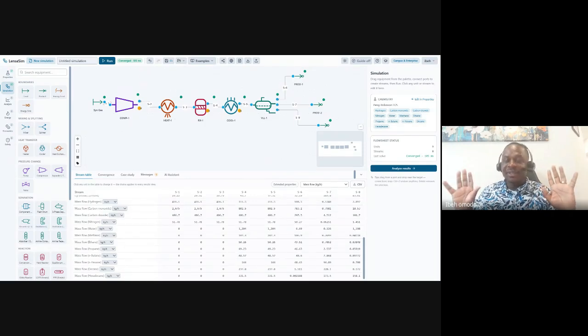Does it make any sense? Aha, that's what I'm saying. So this is the gas. This should have more gas, but if we want to make the conversion more realistic, we need to put a recycle stream so that the unreacted gas will go back into the feed, get heated up again, so I can have more of my products.